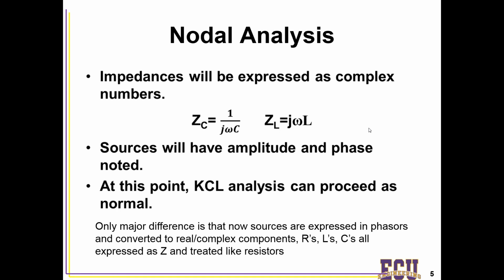This is very important because what that means is at high frequency, this Z of C is going to be very low. It's going to be approaching 0 as a high value of omega comes in here. As a low value of omega comes in for the L, this is going to behave like a short. A low value here, this is going to behave like an open.